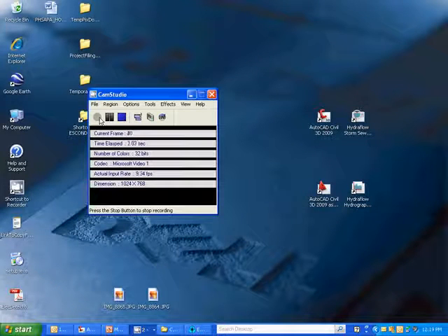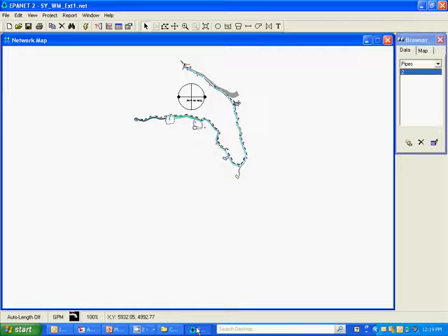In this section I'm going to start to populate the EPAnet model and put in system components. Here's the model I brought in the background map to earlier. You can see our scale there. The pipe I put in is still there along with the nodes. We want to erase those because they're irrelevant to our model now.